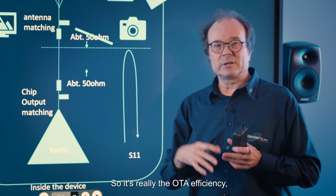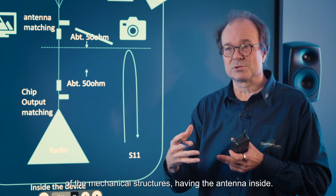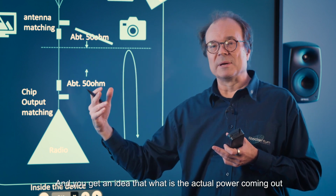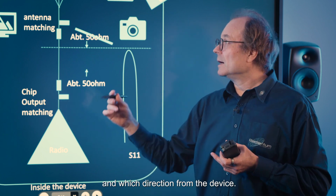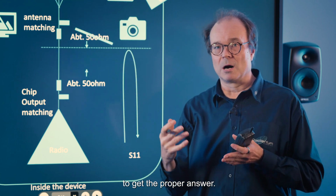So it's really the over-the-air efficiency that you can simulate, with 3D simulation of the mechanical structures having the antenna inside, and you get an idea of the actual power coming out and in which direction from the device. In the simulation you need to model these different elements inside to a certain level to get the proper answer.